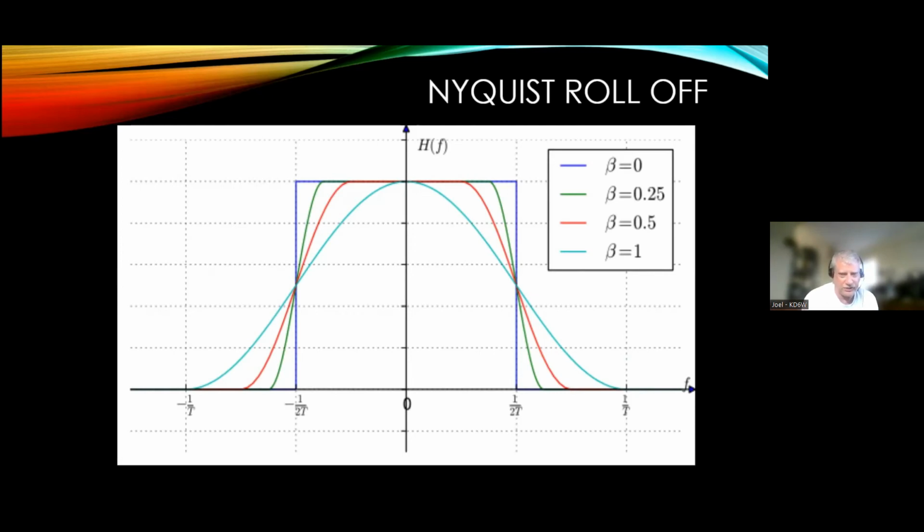0.25 is actually pretty simple, but that's the one where it's going to have some spectral regrowth in the transmitter, because the linear amplifiers are going to get this hash created from all that switching coming from the modulator. So we like 0.25 because it's as close to 0 as you can get. You're not trying to be a square wave, but you're trying to sneak right up next to it. And you don't want to be a sloppy 0.5 because that's just not strong enough.